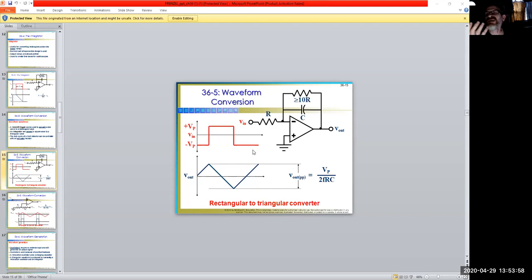Because if I had a time period of a millisecond, and let's say I had my pulse on for 500 microseconds, then on would be half of the time period. So that would be a 50% duty cycle. And so basically you look at duty cycles as how active it is compared to the whole time period.